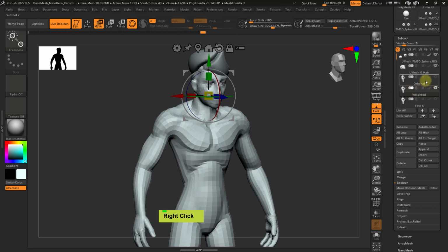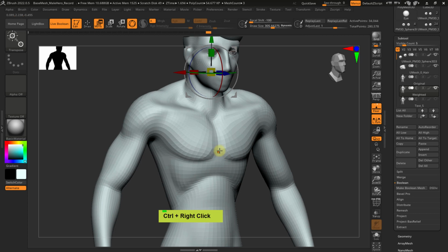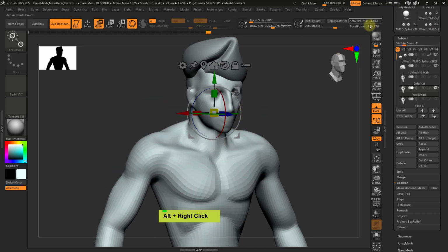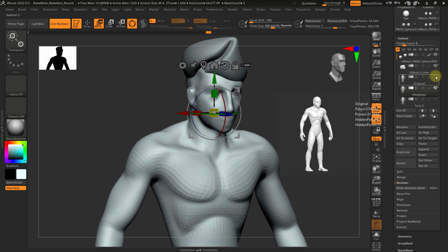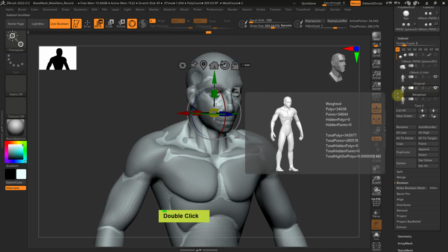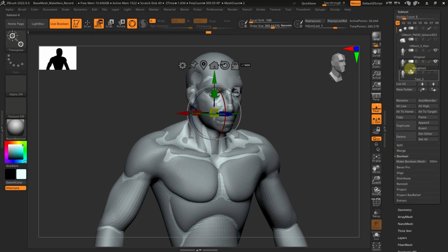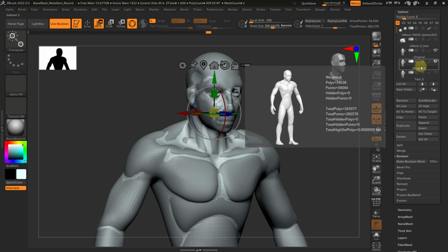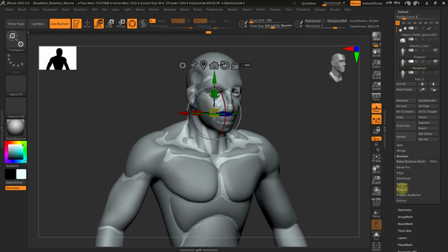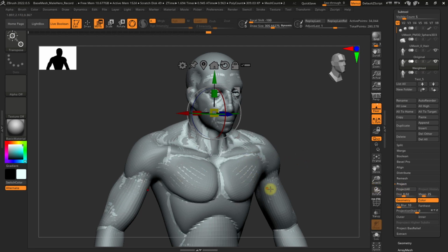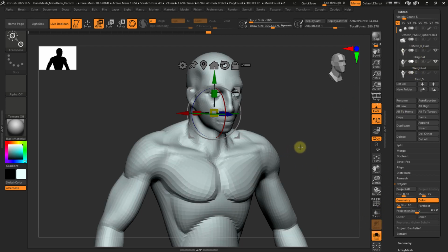And the weighted mesh, sorry, let me turn this off and show just the weighted mesh, and press Ctrl D to subdivide it. When I'm subdividing it, there are way more polygons now, about 34,000. I will turn back on the original mesh, and everything else, eyes and so on, is turned off. Here we have something called projection. On top there's the original. On the bottom there's the recalculated weighted mesh. So I can hit Project All, and it will snap my surface onto the underlying mesh surface. Let me show you the isolation in solo mode.